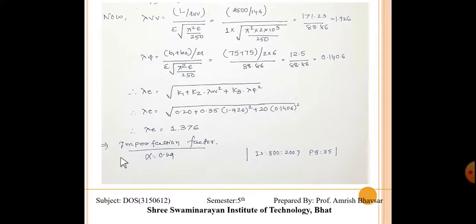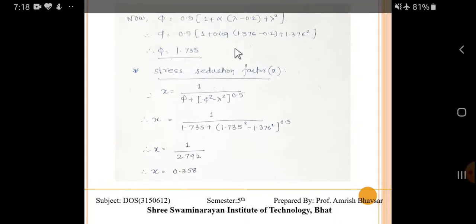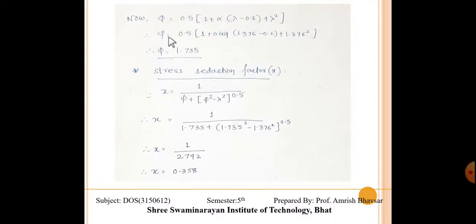After getting lambda, we have to take alpha, and alpha is 0.49 for class C, that is given on page number 35 of IS 800. So alpha and lambda will give us the phi, and we have the equation for the phi, right? So we will get phi is equal to 1.735.